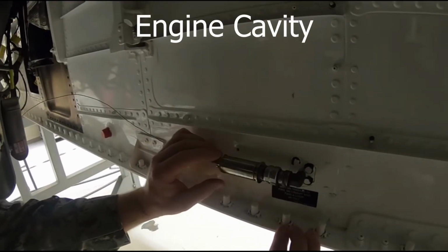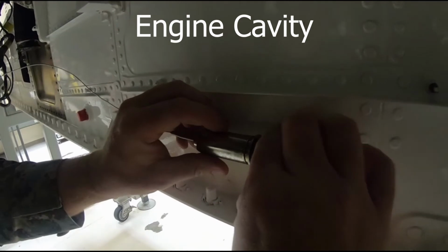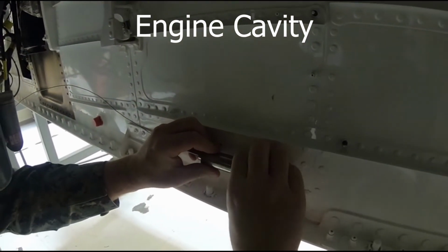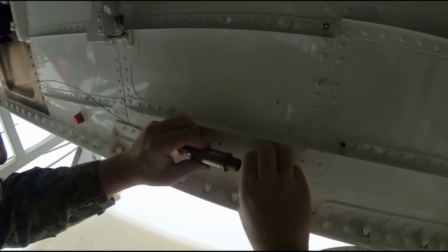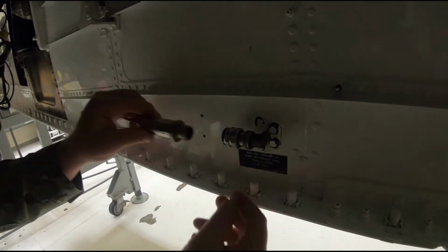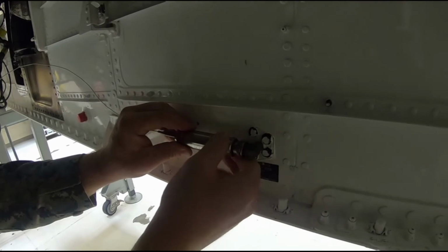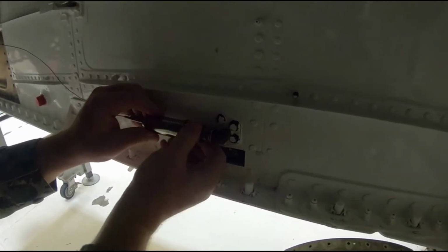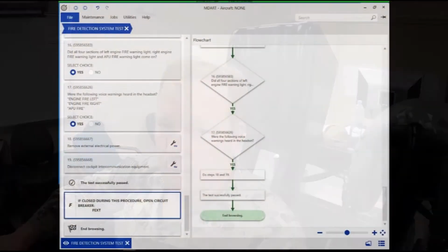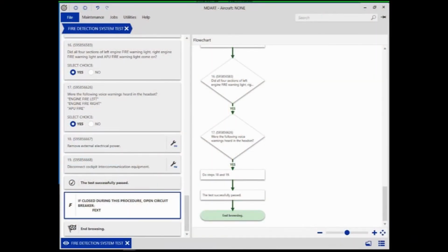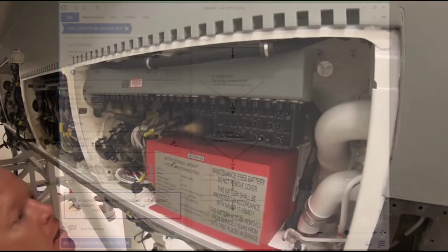After using MSP codes to locate the suspected failed element, disconnect the cannon plug and then slave in your known good element. Ensure that it's connected firmly, and then perform the loop A or loop B test as applicable. If the test is successful, follow all steps to remove external electrical power.